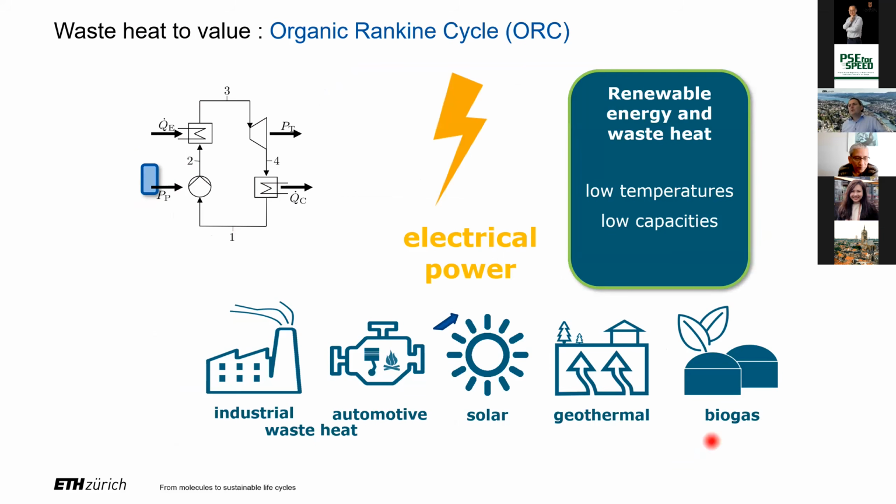But we do have other heat sources that are more sustainable. We have waste heat, industrial or maybe automotive. There might be solar power, geothermal, or biogas. And these heating sources are much more sustainable than those from fossil resources. So the idea that has been advocated is, let's continue using heat-driven power cycles, but let's replace the heat source by something more sustainable. And the nice thing is that you can basically employ the same power cycle: your working fluid is compressed, you apply the heat to generate high pressure steam, you expand the steam in a power cycle, and then you condense it again.